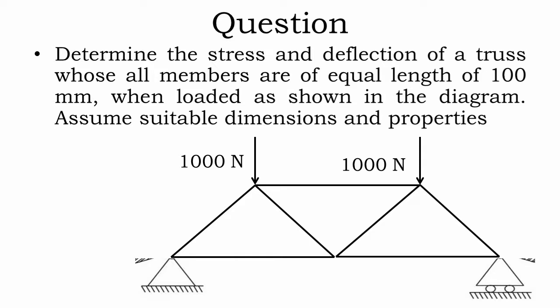We are going to draw this truss in Abaqus, and then we are going to apply concentrated force on the 2 points, and we are going to find out how it deforms. Now we are going to give the boundary conditions as usual. We are going to apply the load. So first of all, to draw this in Abaqus, our first primary aim is to find out this point in a graph sheet, like in x-axis, y-axis.